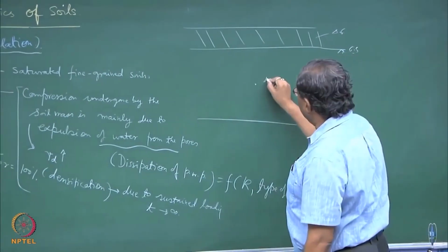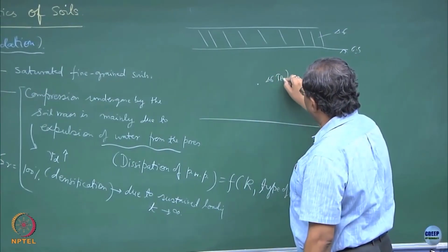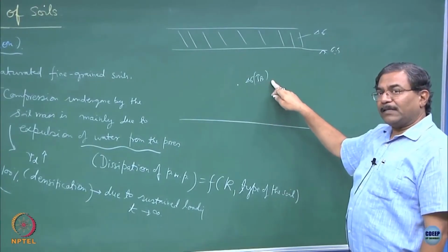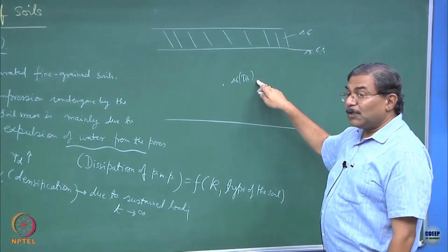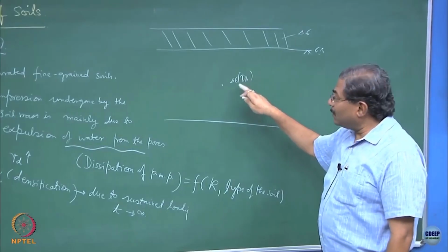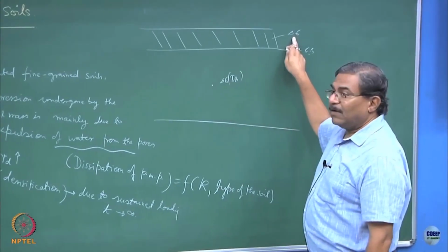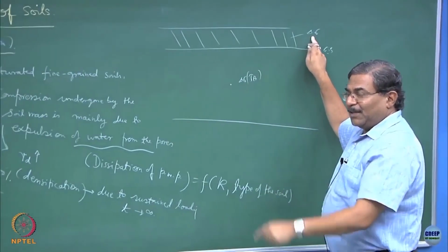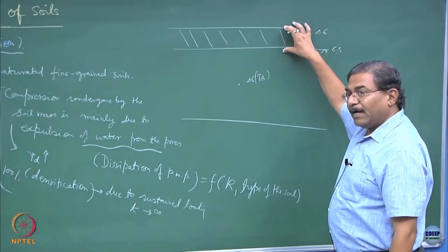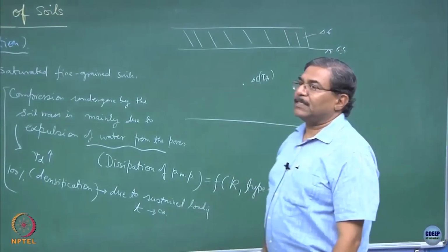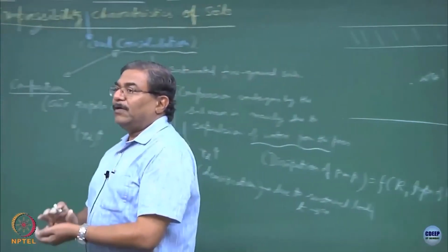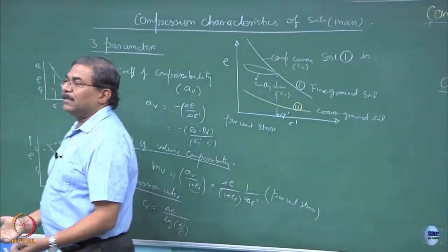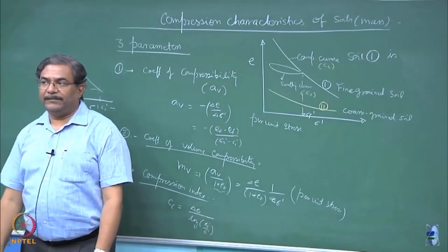So this will become delta sigma multiplied by IB, okay. You know what is IB? Influence factor, very good. The consolidation is going to get initiated because of this delta sigma over a period of time under sustained loading. So whatever you are compacting and creating a pad, if you are not careful in designing the systems, keeping in view the settlement response of the soil mass, they are going to fail.